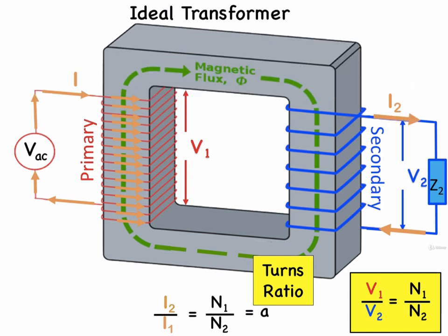Let's take another look at this transformer setup with a load in the secondary of the transformer. And there's going to be current flowing in the primary as we have calculated, and there is a voltage drop across the primary coil. So the power supply sees an impedance because it's reflected due to the impedance on the secondary.